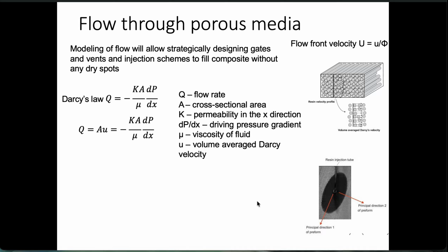One assumption, again, if you go watch the lab video, we are going to have a better understanding of this, is that one of the assumptions we are making is the flow front here that is moving in this direction is moving uniformly. So flow front, there is no curved flow front, essentially. It is moving as a line, which is obviously not correct, but it will give us a good understanding of the permeability with a very low degree of error. So that's one-dimensional flow assumption. That is the main assumption we are making here.